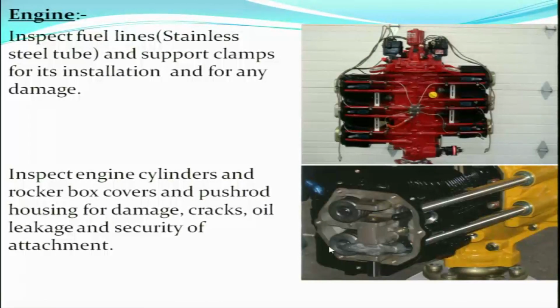When the rocker box covers are removed, there is a gasket on the rocker box cover. That gasket is also replaced. We are not supposed to reuse the gaskets. In case it is removed, then new gaskets have to be installed.